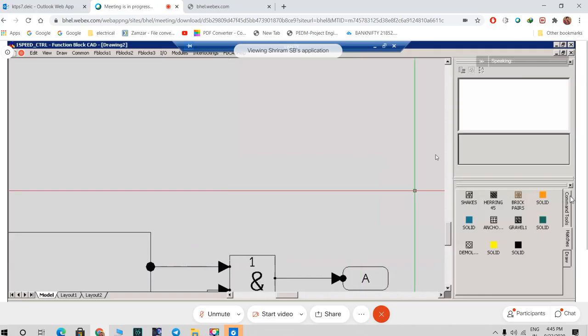We did not get it the second time even after we attempted. That's what I am saying. You cannot get it unless and until that watchdog is acknowledged. If you want to give one more off command, first you have to get that watchdog acknowledged. For that, whatever in the field side has caused the watchdog has to be corrected first. Then once that watchdog is acknowledged, you will be able to give a second time command.